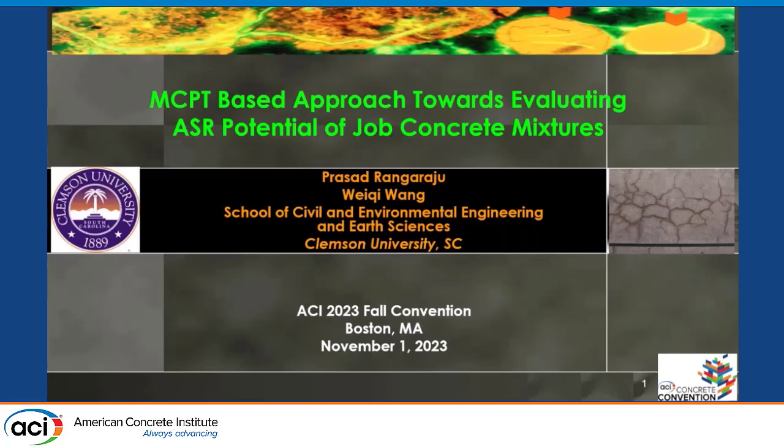All right, so if you haven't already heard enough acronyms of ASR test methods, I'm going to throw one more, which you probably already heard again: MCPT, the ASTM C1260 test, which is what I'm going to talk about. It is this MCPT-based approach towards evaluating ASR potential of job concrete mixtures.